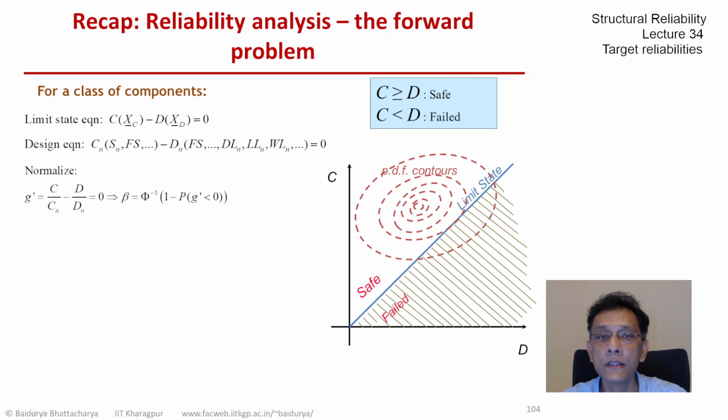I could have the limit state against collapse or creation of plastic hinge or some such limiting event, and the design equation could be instead verifying against yield after an elastic analysis.